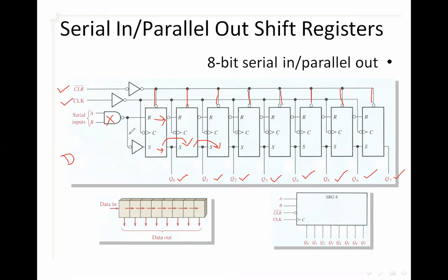Now here I have a bubble, here also I have a bubble, which means it is a true value which enters. It's a true value, right? Say for example, I gave 1 here, and then I gave a 0 here, so what should my output be? 1 into 0 is 0, so inversion gives 1.